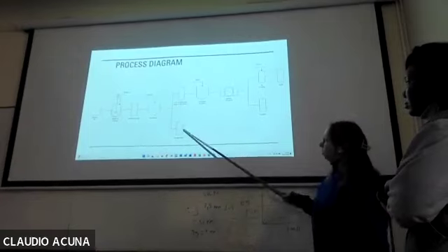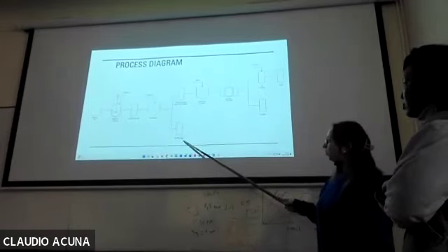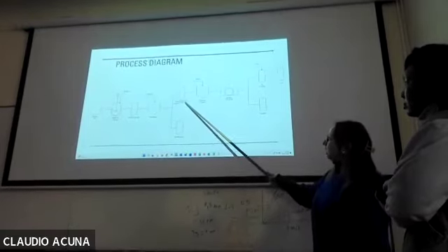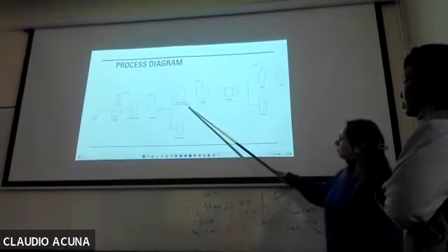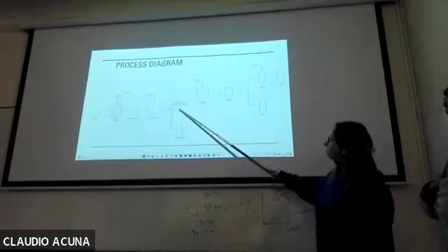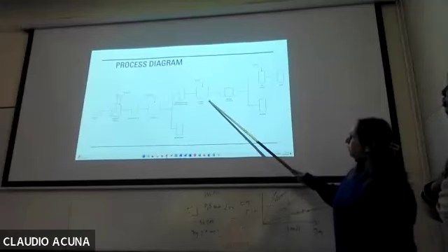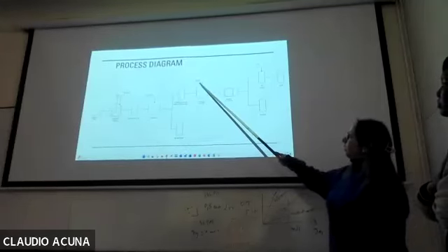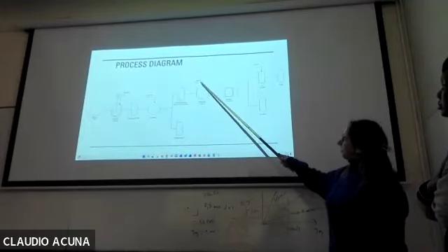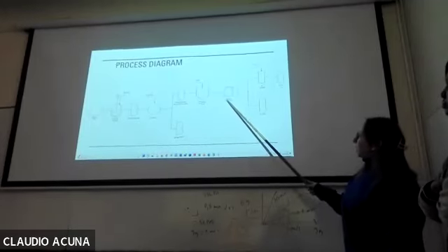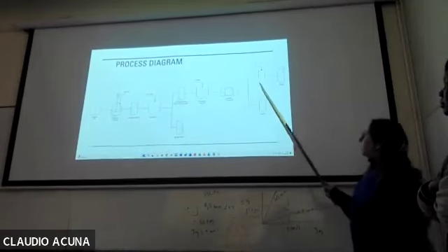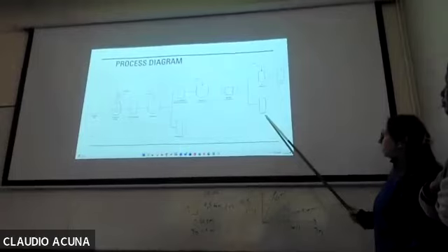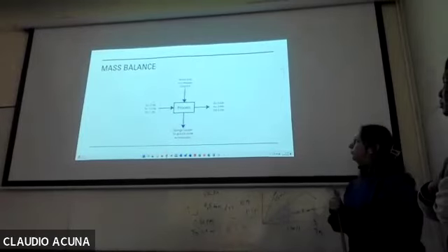And here we have two products. One is the sponge copper, and then we have the liquid that contains arsenic, zinc, and cadmium solution. This is our focus. Then, like I told you, we precipitate the zinc and cadmium with sodium carbonate, and then we have the filtration process. We separate the arsenic in solution, and then the zinc and cadmium.